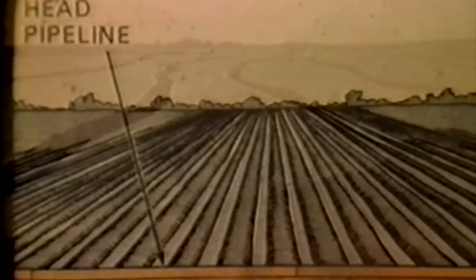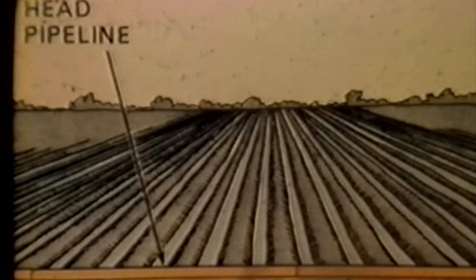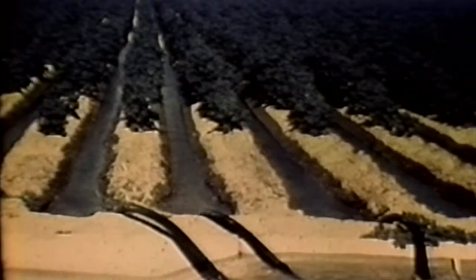The level furrow type of surface system is the same as the level border type, except for the addition of furrows. When irrigating, a stream as large as the furrow will carry without causing erosion is turned into each furrow by siphon tubes or gated pipe. The water is allowed to stand in the furrows until it has been absorbed into the root zone below the furrows and in the ridges between the furrows.